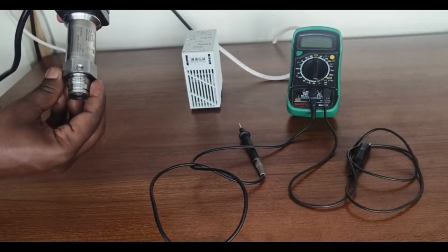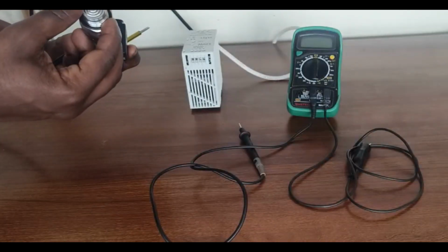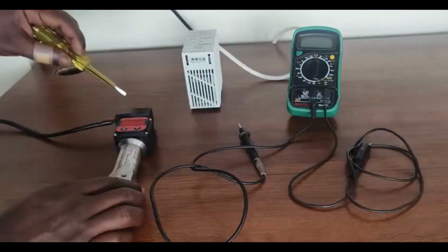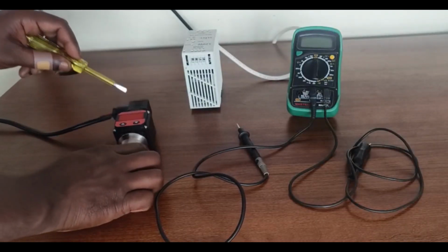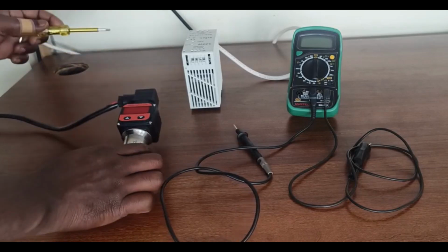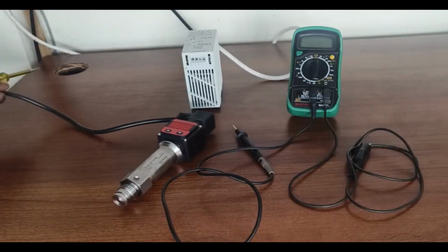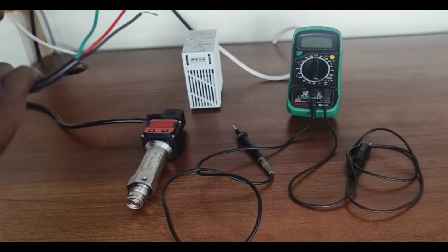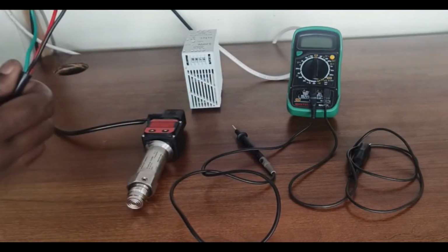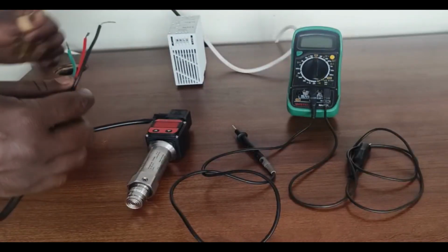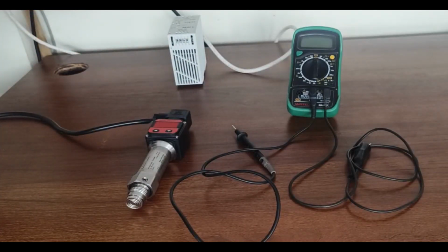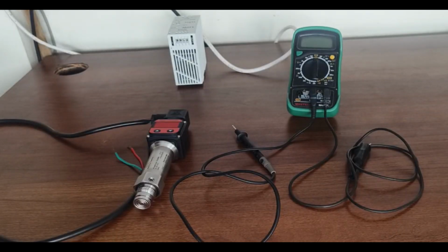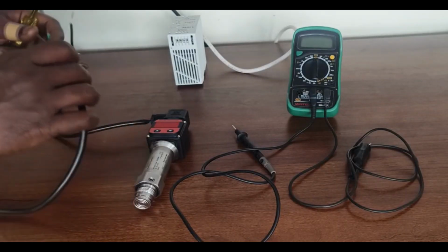Third, a Baumer-make pressure transmitter with a 1/2-inch flush diaphragm process connection. Fourth, an external digital display to monitor pressure in bar. And fifth, a 3-core power cable, 1 positive, 1 negative, and 1 shield wire. We're creating a loop-powered circuit so that we can observe both pressure in bar and the 4 to 20 milliamp output simultaneously. Let's start wiring.